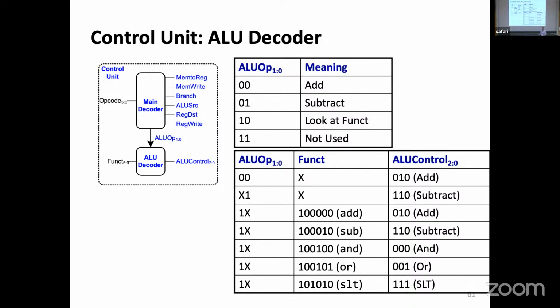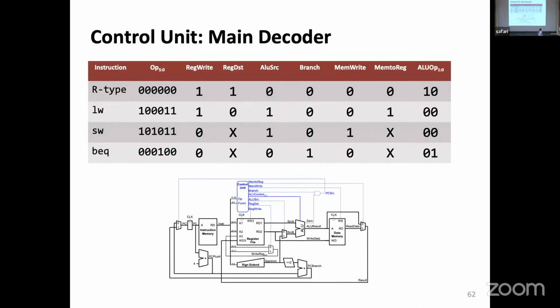Once you have these tables, it is easy to write your code, or even if you are up to it, you can also do the optimization yourself. You know, we saw all these Karnaugh maps and things, how we can minimize things. And for the main decoder, you realize that this is the table we already walked through. Given the instruction, once we look at the operation code, we know what the individual control signals should be. So at every step of the way, what we say decoding is looking at the instruction and deciding on the rest of the way, controlling how the data will be flowing through.